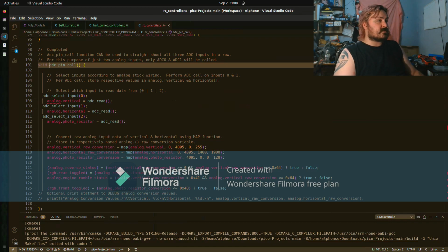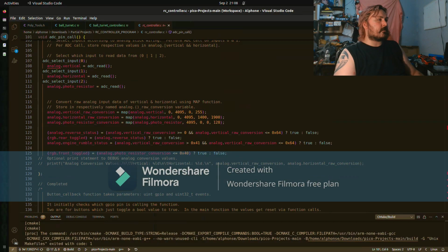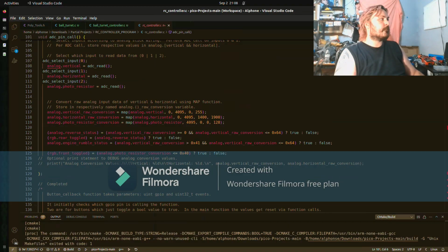So it can read those, and then it will map those values, and I should actually probably use DMA to go straight from the mapped value to where I want to store it, or right to FIFO actually, which would be my RF. So I could just have that value mapped, have it buffered, and then transfer it directly. Maybe not DMA because it's SPI. From what I understand, that's a state program. So we go there.